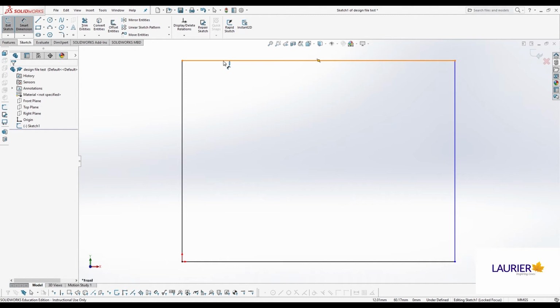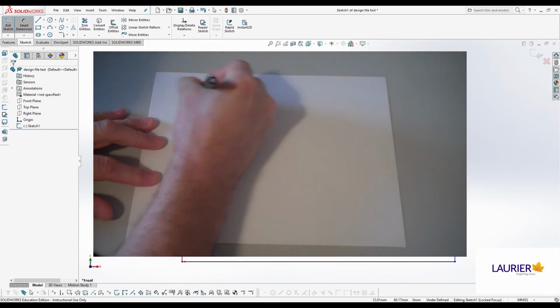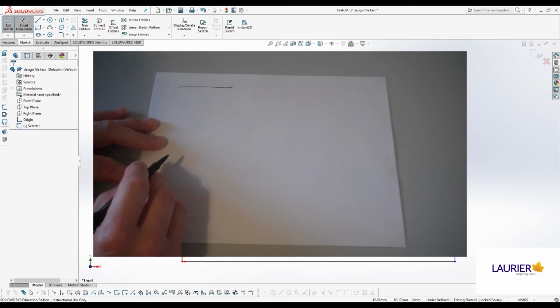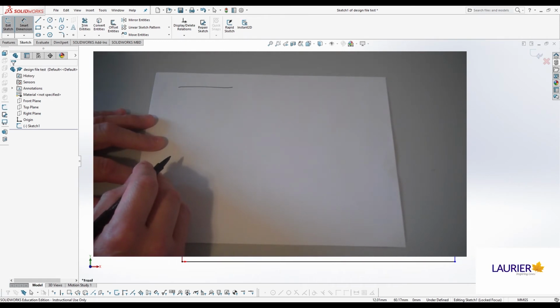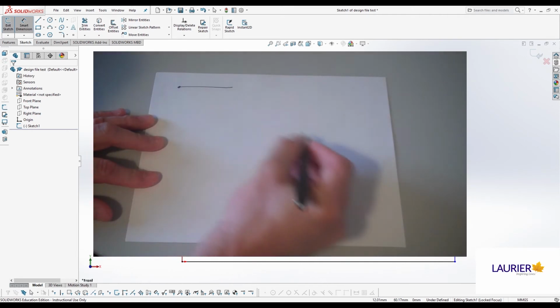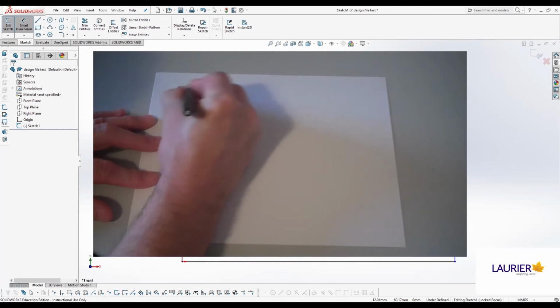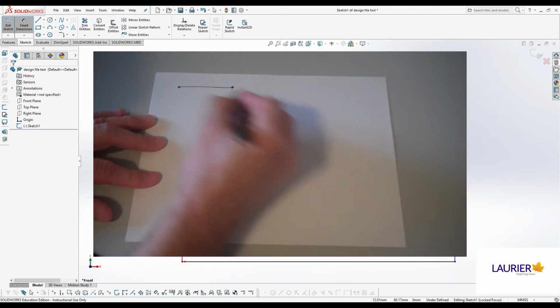To understand how an entity interacts with the type of objects we're trying to measure, let's take a straight line. Now I'm going to ask you how many entities are in that simple straight line. And I'll often get a guess of 1 or infinity. And the correct answer is actually 4. We've got a beginning point, an end point, we've got the line between them, so those are 3, and then the CAD supplies us with a midpoint.